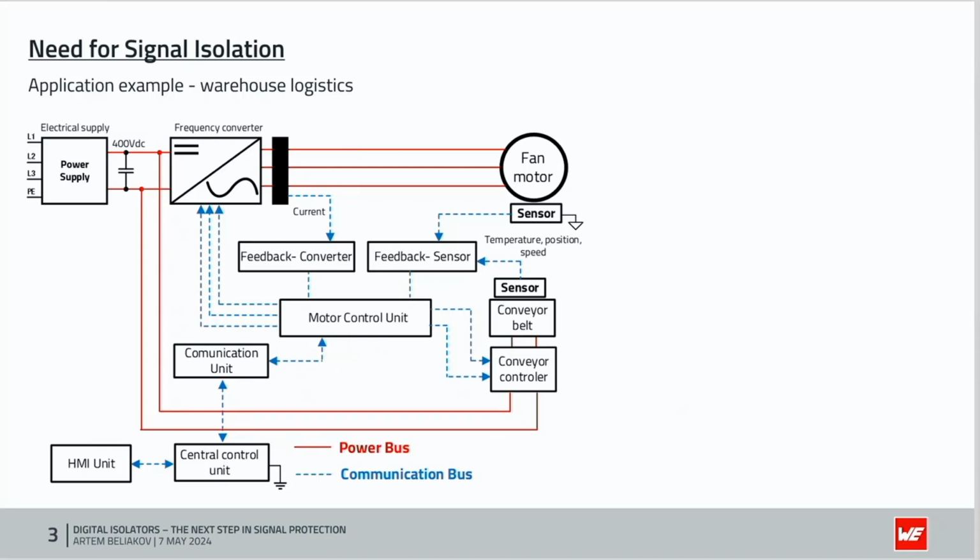It means long wires. And that also means that measured signals can be disturbed by potential differences on the line. We definitely need to organize some isolation barrier between two devices for prevention of ground potential differences. Of course, we also need it for reliable data transfer without any mistakes or errors.